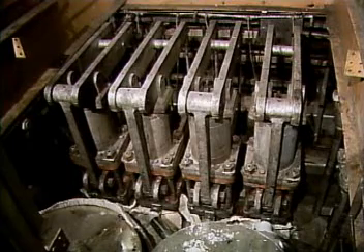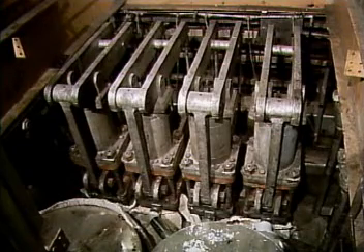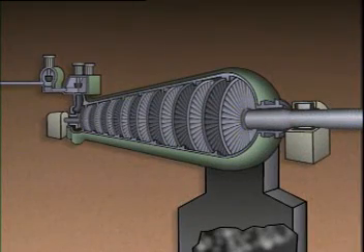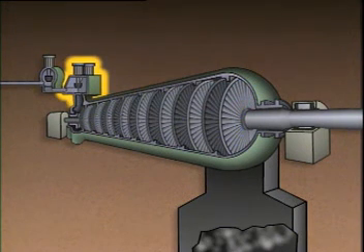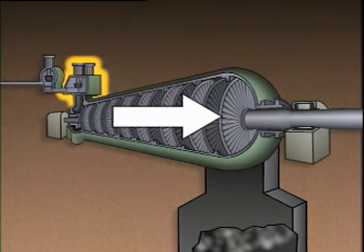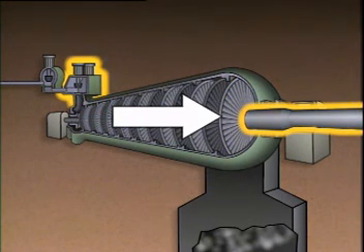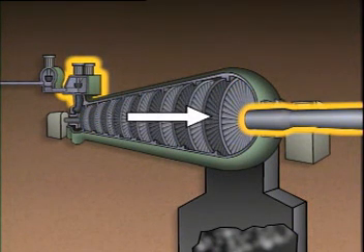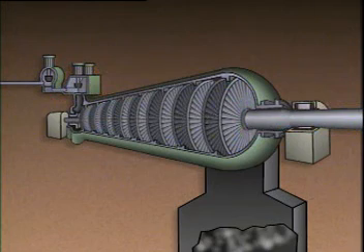The turbine steam control valves are located in the main steam line to the turbine. They are used to regulate the flow of steam into the turbine. In this illustration of a typical turbine, the steam control valves are located here. If more power is needed from the generator, the valves are opened wider. This causes more steam to flow through the turbine, more mechanical energy to be received by the generator, and more electric power to be produced. The reverse occurs when the steam control valves are closed down more.